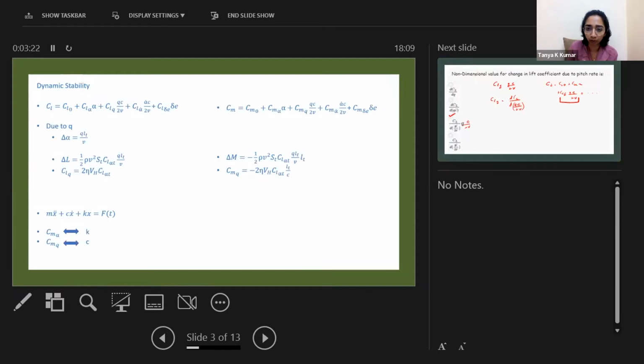So when you move on to an aircraft, you have the aerodynamic parameters CL, CD, CM, such, okay? So we have assumed the linear expansion for the CL was CL naught plus CL alpha into alpha. So it was this term and the control term. Delta E is the elevator deflection and the elevator is the control surface. So this is the control term and this was the original term that we used, okay? So these were the 2 terms that we had utilized throughout the past few weeks for static longitudinal stability.